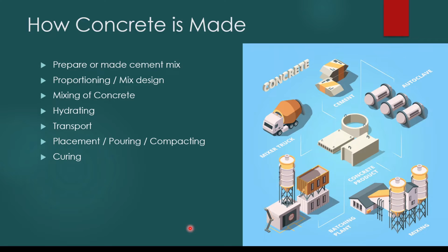So we can use strain gauges and measure the weight of the cement and all that. You know cement is in silos like this. You have the aggregate, then you can put it into the bin. Therefore, we use weight batching to make it easier when we do the mixing in the batching plant. I want to extend this discussion further on the mix design. When you do a mix design, firstly you do the mix proportions.